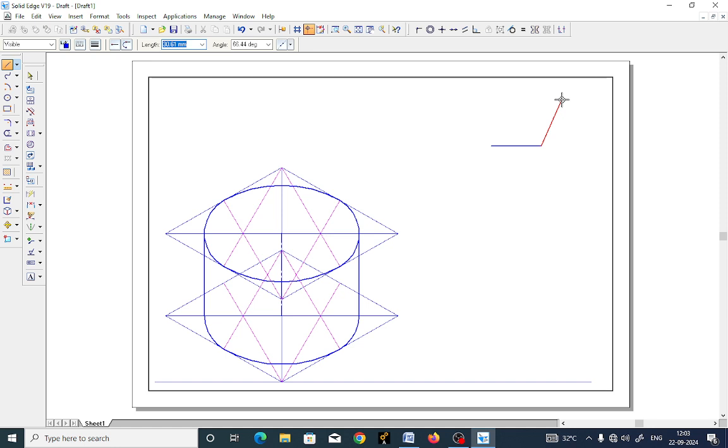Now as the outside angle of this pentagon becomes 72 degrees, let us complete the first pentagon. You calculate the outside angle, then you go for add on angle for edge wise or for side wise. Now you got a pentagon. Next you need to construct a rectangle covering all corner points of this pentagon.